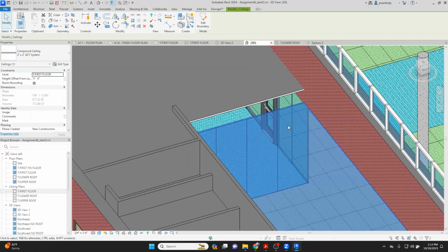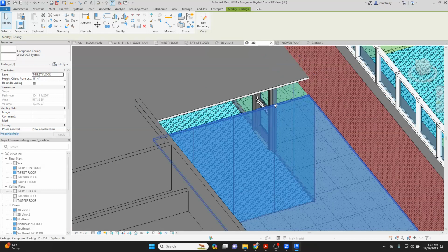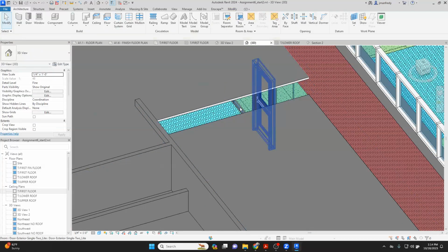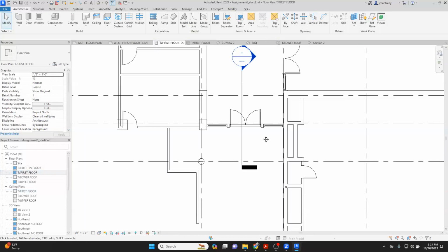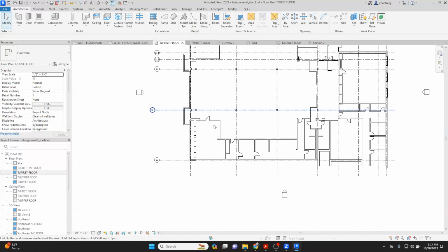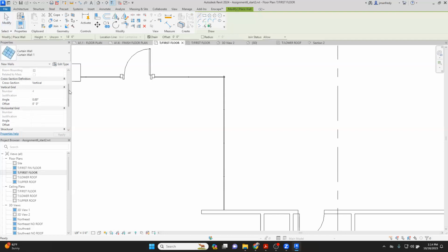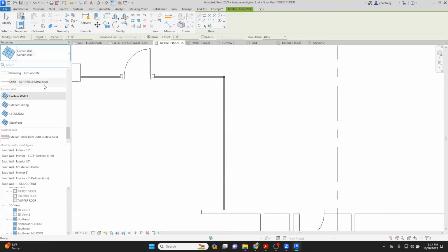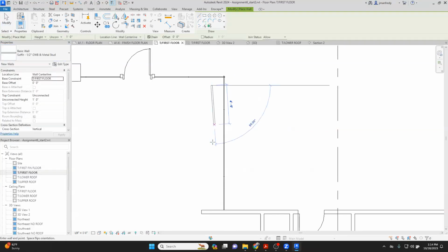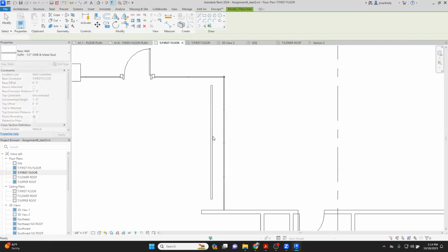It's above this ceiling here. This is an 11'4" ceiling. So I don't want to make glass up there. I want to put a little wall there. So luckily Revit has a wall. So I'll go to the floor plan here. And there's a little tiny wall you have to put there called a soffit. I'm going to draw it here on the floor. Architecture wall. And one of my walls in the type selector is called a soffit. And if I put a soffit right here, there's a soffit.